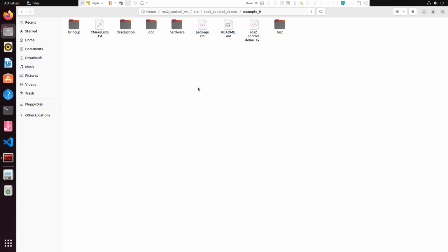If you remember the ros2 control, there are some things that we have done, like adding some tags in the URDF. Then we started the control manager and loaded the controllers. The controllers are written in a YAML file, and they will be loaded by the control manager.